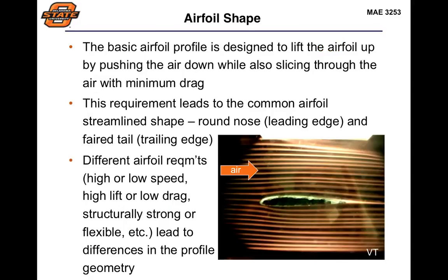Now, as we'll see in Xfoil, it's really only good for airfoils. It's designed to be able to calculate these parameters over a streamlined shape. And that's very important. When we talk about a traditional airfoil shape where we have that rounded leading edge and that faired trailing edge in the back, in order to give us a compromise between good lift, high lift, and good drag, meaning low drag, those are the types of cross sections and profiles that Xfoil and other panel methods are really designed to be able to study.